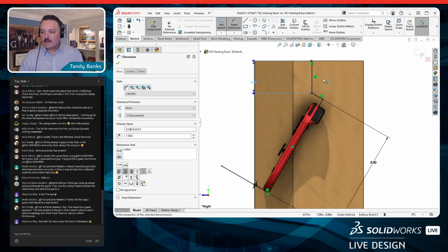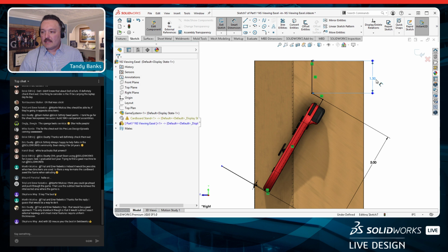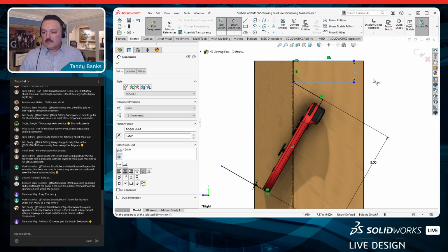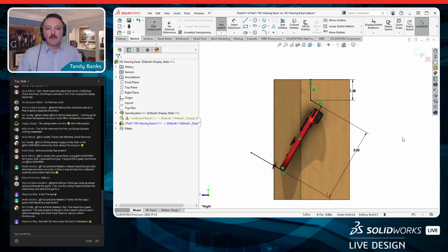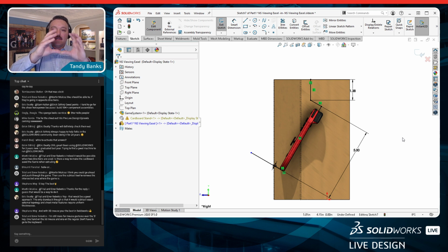What's that look like? It's not bad, but maybe not exactly what I want. Let's look at 1 inch. Ooh, that's too much. Let's go like 1 3/8. Looks good to me. It's about what I want. And if you'll notice, I'm living dangerously here today. I'm working with an open profile, meaning it doesn't come back and touch itself. That's one of the techniques that we can use in our cut tool: we can use a single contiguous profile, and it's going to create a slicing plane, much like a surface would. It's kind of like a surface cut for solids, right?